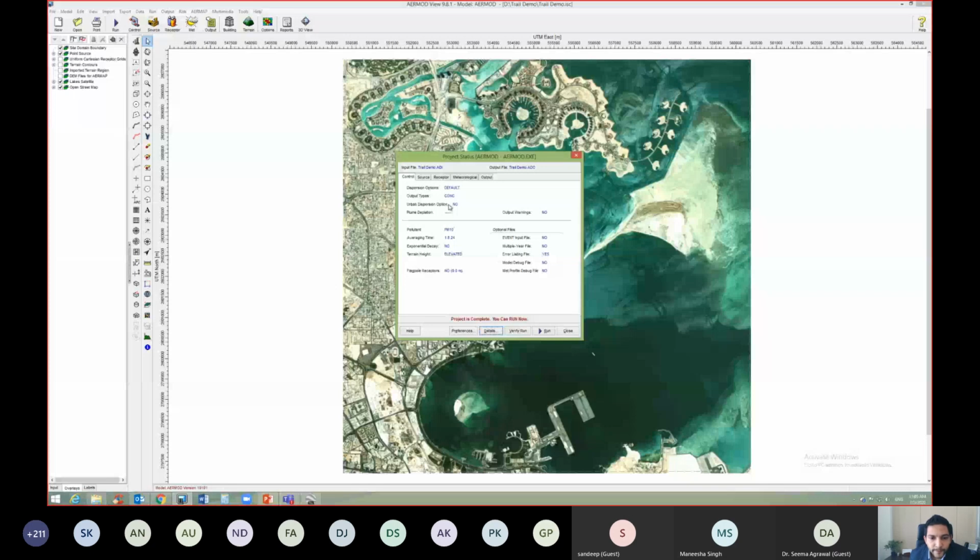So we are going to do the modeling for particulate matter for averaging periods of 1 hour, 8 hour and 24 hour, for elevated terrain, and the source is one DG source with about 441 grid receptors. Meteorological data from the year 2014, and we will get values for 1 hour, 8 hour and 24 hour.